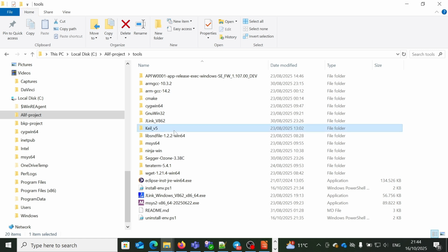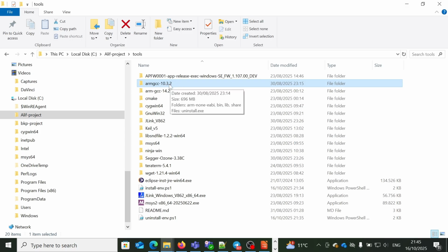Now, in terms of tooling, our Wadix Tools GitHub repository offers quite a big number of tools and applications. Nevertheless, for our makefile based project, we will need mainly the ARM GCC compiler. This is the ARM GNU none-EABI GCC compiler from ARM, and this is targeting mainly the ARM Cortex-M microprocessor family. Our makefile project will be an ARM Cortex-M3 based project.